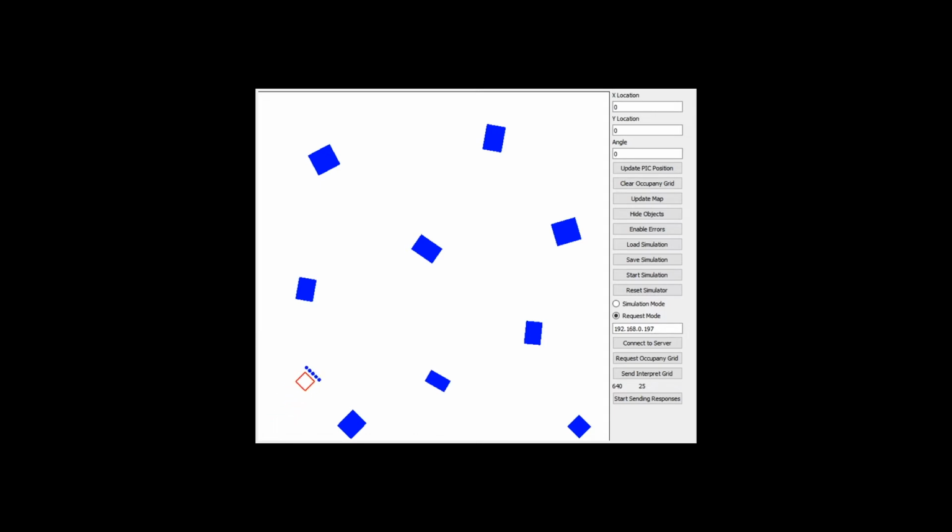This is to ensure the rover does not get stuck in a region of the map due to repetitive and predictable behavior. The rover initially moves forward in a straight line while requesting sensor data from the target locating module. Once the sensors indicate that an obstacle is 15 centimeters away, the rover stops. Then it picks a random direction to turn and rotates a random number of degrees.